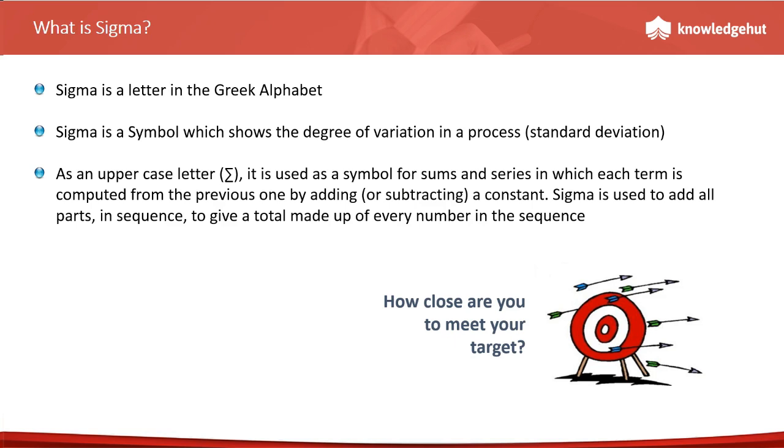Now, in this situation, your lower specification limit becomes 5.7 inches, which is 6 minus 0.3. And since he said plus or minus, the upper specification limit becomes 6.3, which is 6 plus 0.3, right? Anything which you produce between these limits, that's 5.7 to 6.3, is good for the customer. Customer is going to accept it. However, anything which goes beyond that is a defect.